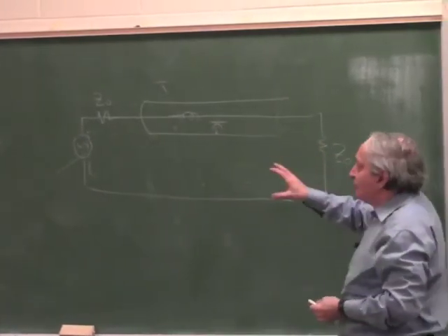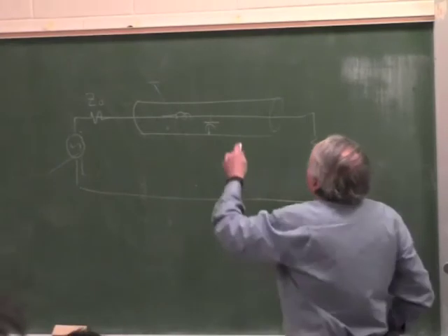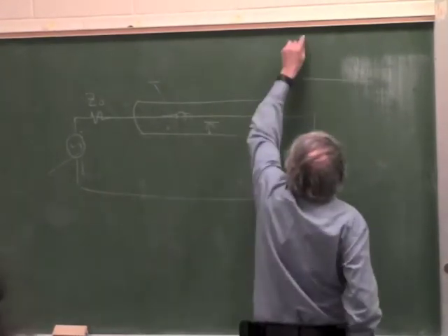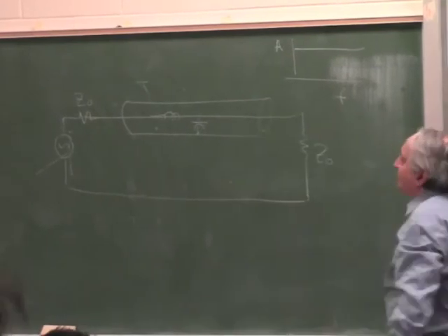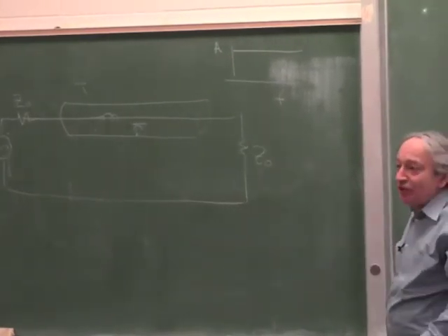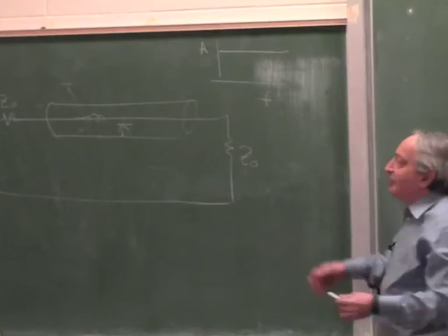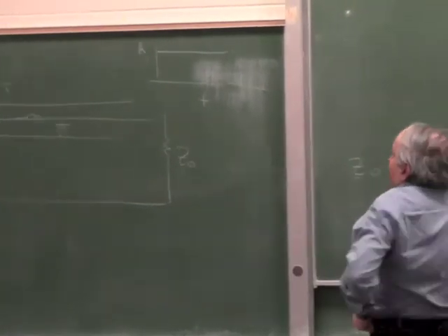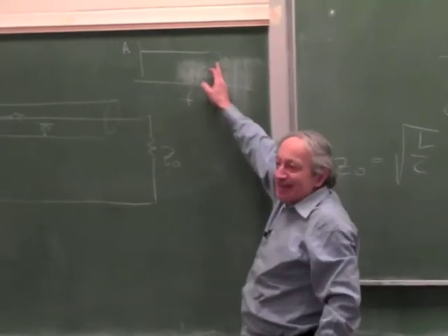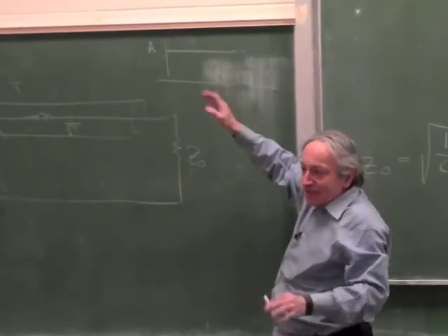Because it will behave purely resistive, the Bode plot, if this is amplitude and this is frequency, will be flat, totally independent of frequency. Eventually, everything breaks up at very high frequencies, so it will fall down, but this will happen at hundreds of megahertz, where everything gets complicated.